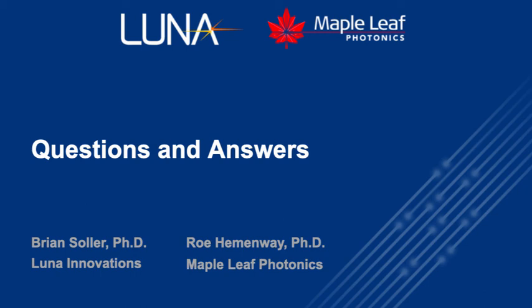This is Brian. The OVA is calibrated. It requires a calibration for amplitude or for loss. It doesn't require a calibration for the phase measurements or polarization. That's all handled internally. But for the loss parameters, the Jones matrix amplitudes, you have to give the analyzer a calibration path.